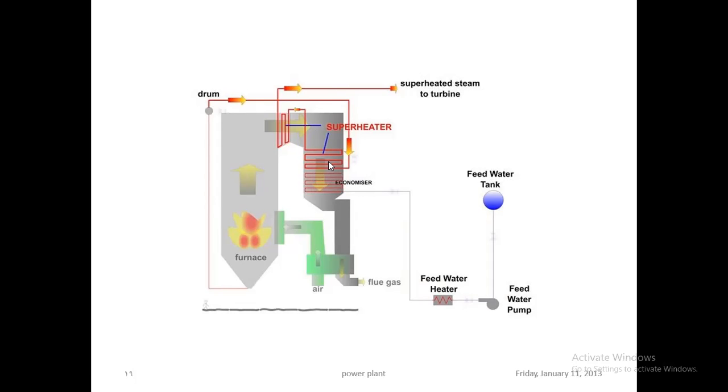At this level we have these pipes, and at the end, superheated steam goes to the turbine. That superheated, saturated dry steam further goes towards the steam turbine and runs the turbine's blades. This steam would be highly pressurized steam. So the main thing is to use this pressurized steam to move the blades of the turbine.